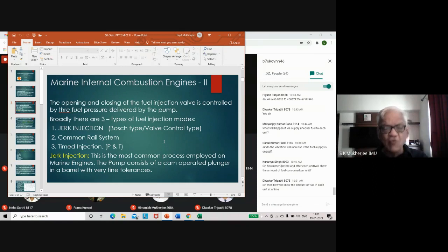And this works also like a tank, under very heavy pressure, and from this pipe or manifold you have individual pipes going to the individual injectors, and the fuel is received right at the nozzle at 2000 to 3000 bar. So all it needs is momentary opening of that injector to allow the oil to come in.